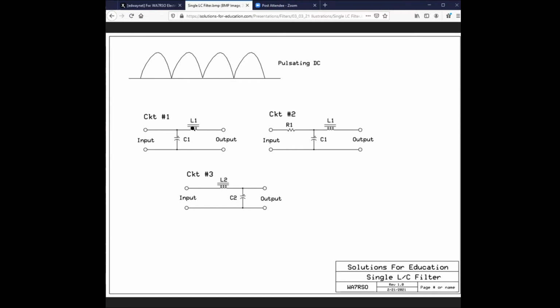How does this guy here resist current flow? What happens is as the voltage rises and as we try to make current flow, the energy that's in the current flow develops what's called a counter EMF, CEMF, and the CEMF opposes the attempt to shove current through it. So if you've got voltage matching it, guess what? No current flow. The faster you try to make it go, the more counter EMF there is.